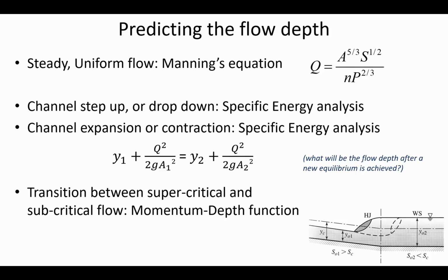Another way that we can diagnose whether the flow regime is supercritical is by comparing the known flow depth to what the critical depth should be. And so this dashed line here is just an illustration of the known critical depth. And remember, for a rectangular channel, we can calculate that relatively easily with lowercase q, the flow per unit width squared, divided by g, all of that to the 1/3 power.